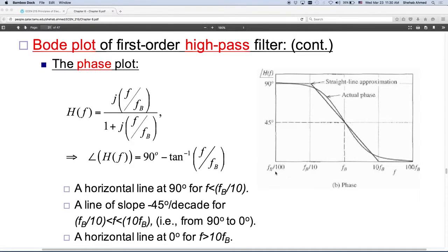So capacitors, what do they do? Capacitors are open circuits for DC. They are short circuits for AC, right? So they are going to act on signals that are AC in nature, and they will not act on DC signals because they will be an open circuit. When they act, and they are the dominant component in the RC circuit, they will phase shift the quantities by something close to 90 degrees. When they don't act on the signal, the quantities will end up having a phase shift of 0 degrees, because what's dominant there is the resistor, since the capacitor is an open circuit.